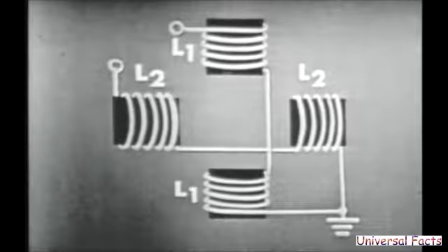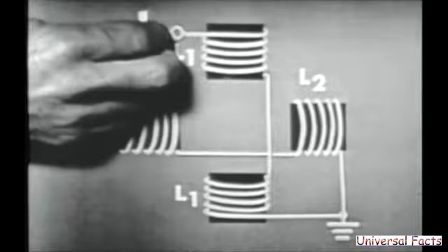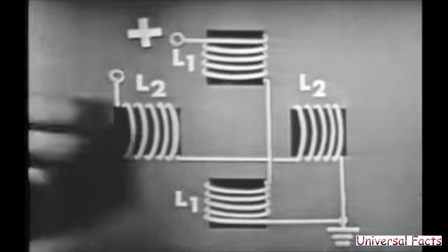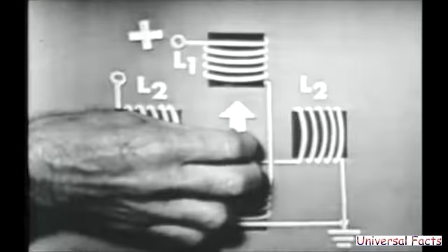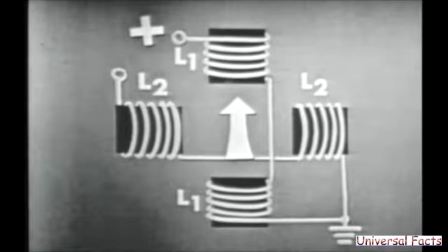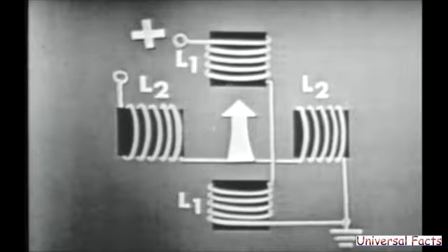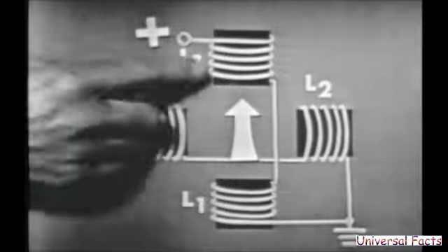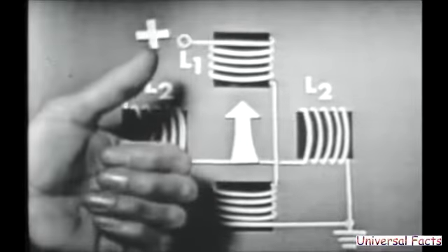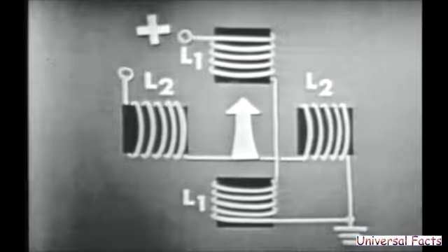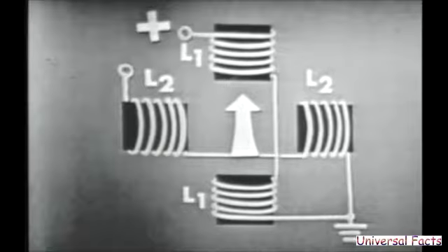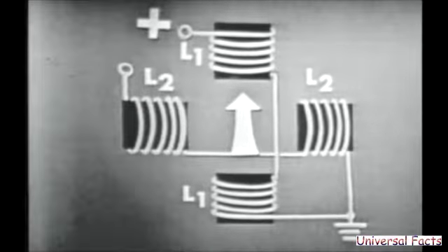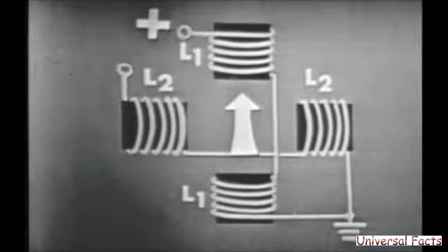So if we supply voltage to just L1, we'll of course cause a vertical magnetic field. Like this. And the field lines up like this. Now, this arrow, like the arrow on our trainer, points to the north pole of this magnetic field. Right up here. And right here, Tom, we should point out that you can apply the left-hand rule and determine the magnetic polarity of these coils. We're not going to take the time to do it now, but it'd be a good idea for the students to do that. They could actually prove that what we're saying is quite true. Right, that's a good point.